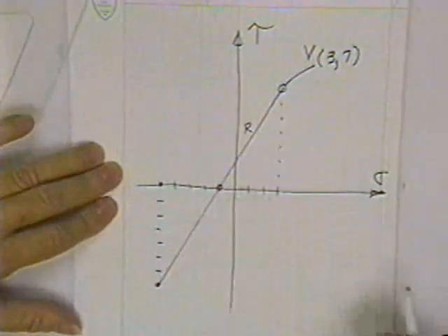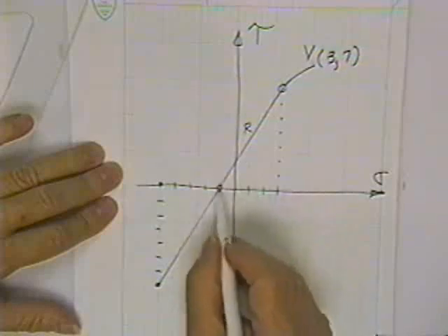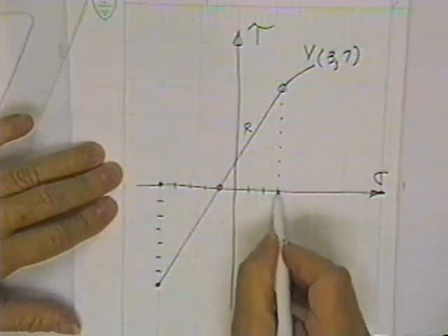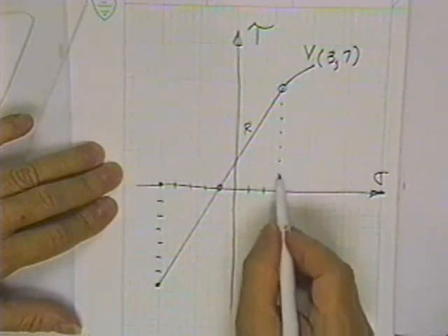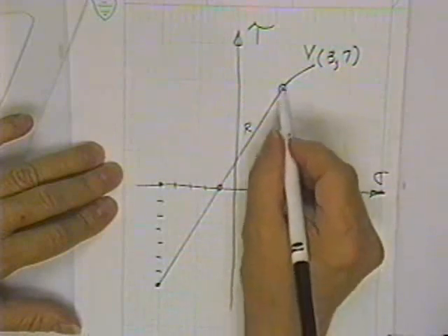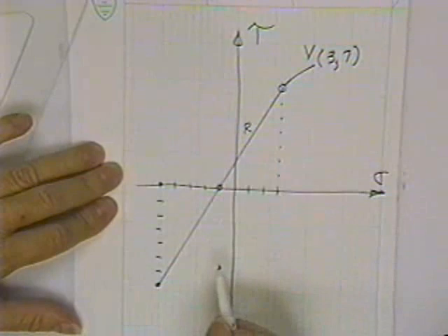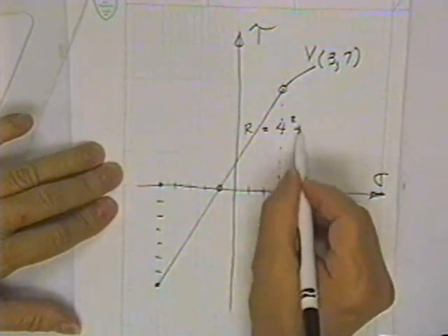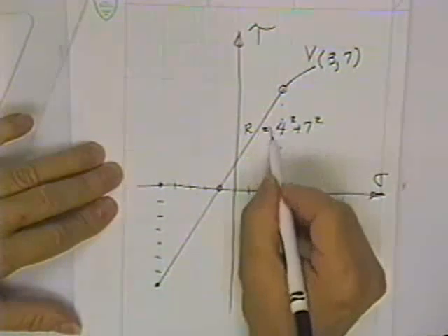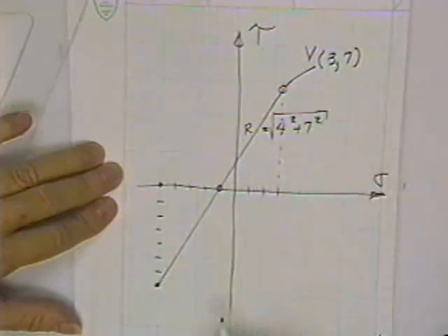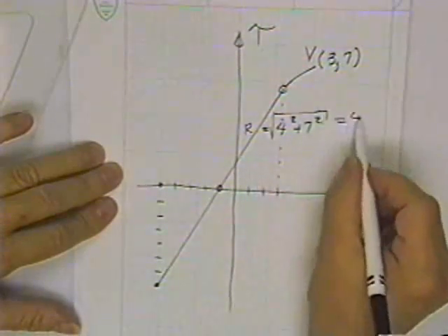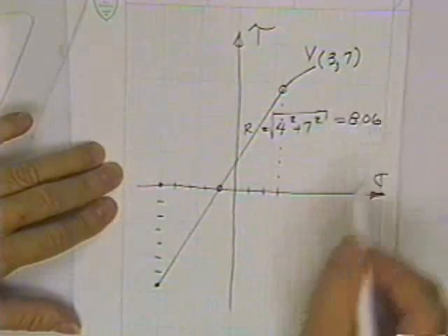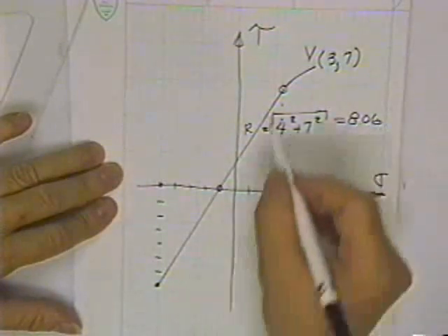This radius is, got a number there for me? 1, 2, 3, 4 squared, plus the following number squared, 1, 2, 3, 4, 5, 6, 7 squared, and then you take a square root. I mean, I just pick it right off my graph. How big? 8.06. 8.06 ksi big.